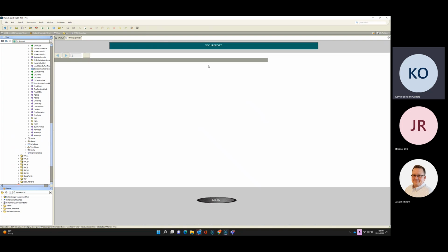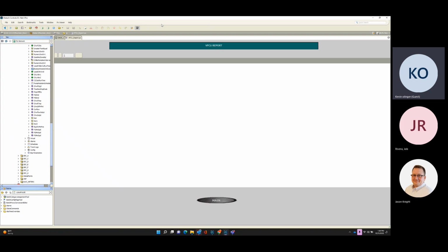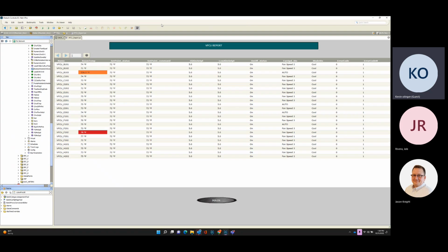So we definitely would want that fire point on all the air handler screens, because that's typically where our troubleshooting is going to take us straight to. And then it would flag us with a red icon saying, oh, that's why it's off. It's in fire alarm. Okay, now he's got to troubleshoot why it is still there. Yep. Let me make note of that.